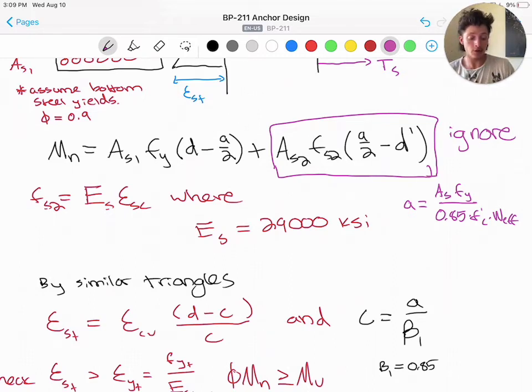And we have all of our equations for all of our numbers here based on the properties of the rebar, the properties of the concrete section, which we've defined earlier. We can calculate A, we calculate C, the distance to our neutral axis, and we use beta 1 from the fact that we have less than 4,000 psi concrete. We take that value to be 0.85.